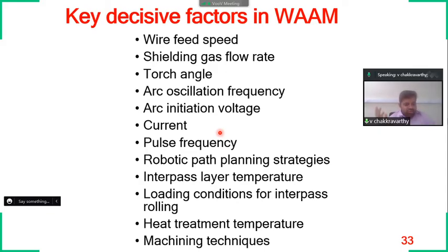Okay, dilution I have shown you previously. Dilution means how much one layer gets infiltrated into the other layer. So that is called dilution. If more dilution is taking place, then more volume of material we need to deposit. So it is a material wastage. Okay, so in order to prevent that, we will maintain an interpass layer temperature.